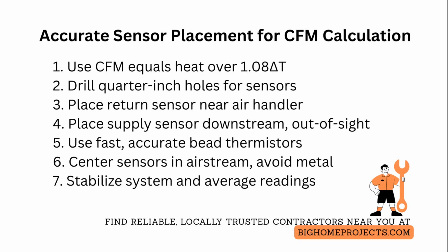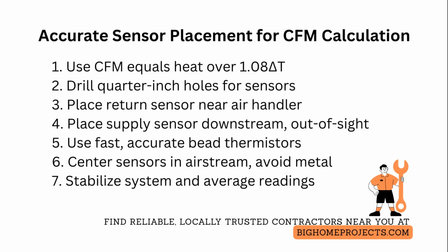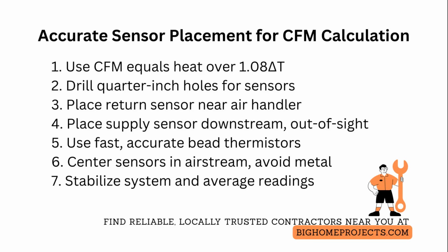Use fast response thermistors or Type T thermocouples with accuracy of plus or minus 0.2 degrees Fahrenheit and insert them so the bead is centered in the airstream, not touching metal. Seal probe holes with removable grommets or foil tape after insertion to prevent pressure and temperature leakage that skew readings.